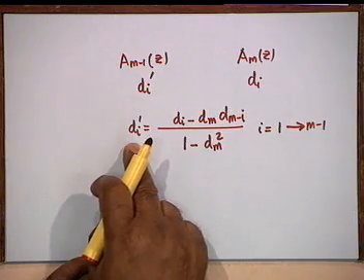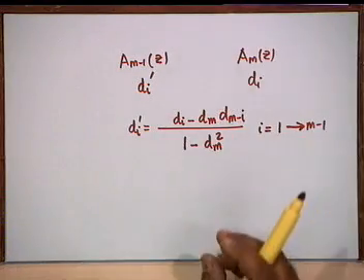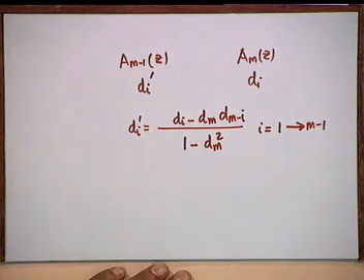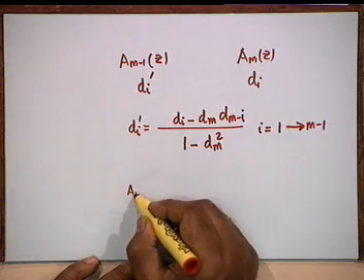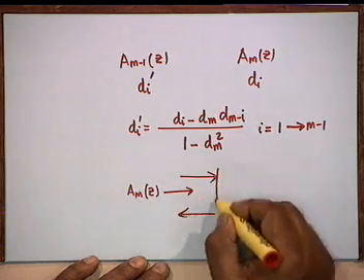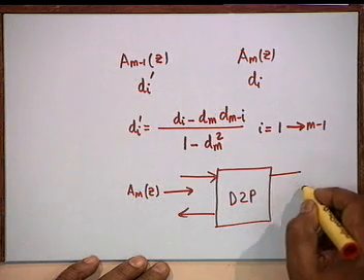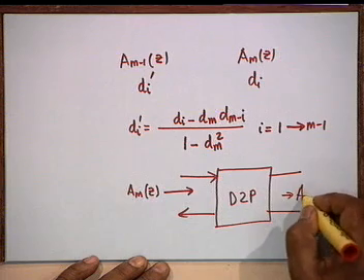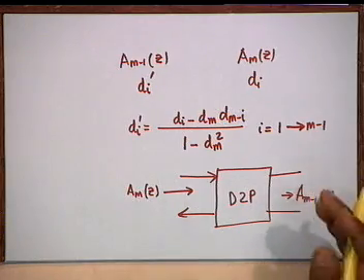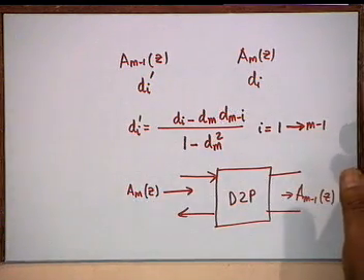This was the stability testing procedure. We shall use this now very judiciously. Now our aim is to construct A_m(z). Let's go back a little bit. As the transfer function of a digital two-pair terminated in A_{m-1}(z), right? Terminated in A_{m-1}(z). I have not shown it as a block because this block is again realized by another digital two-pair, another digital two-pair,